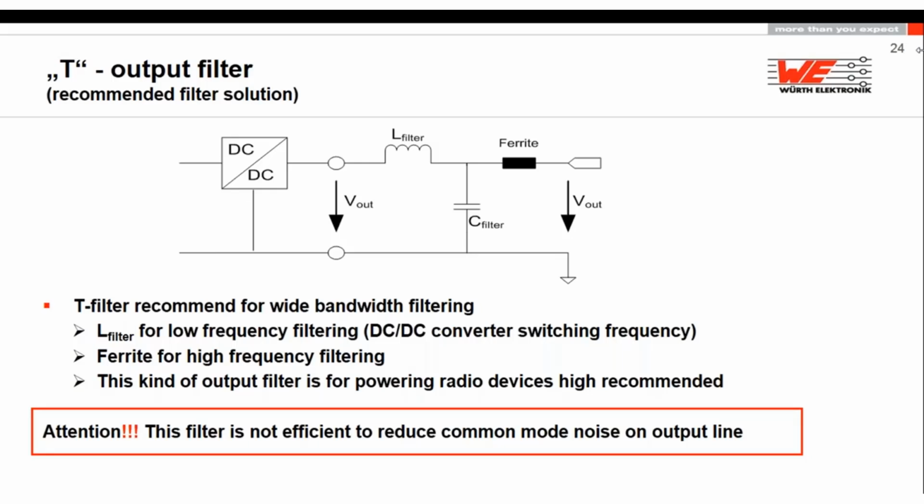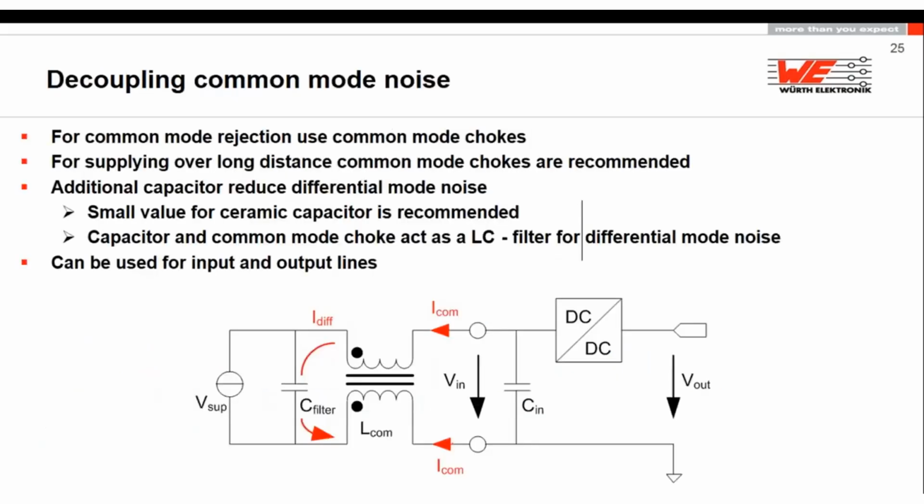It won't destroy your efficiency. Now, if you have something like common mode noise, all this ferrite bead and inductor won't help enough. You have to use a common mode choke as well. But be aware, if you connect the minus to the ground plane in front of the common mode choke and again after the common mode choke, you make a short circuit of this winding.